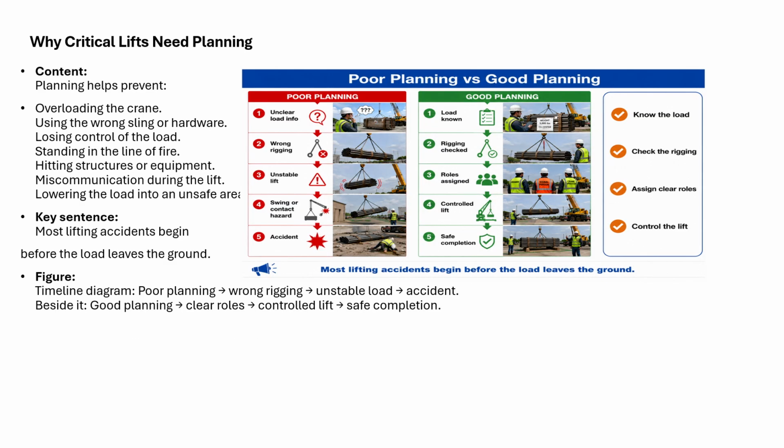Why does a critical lift need planning? Planning helps prevent overloading the crane, using the wrong sling or hardware, losing control of the load, standing in the line of fire, hitting structures or equipment, miscommunication during the lift, and lowering the load into an unsafe area. Key sentence: most lifting accidents begin before the load leaves the ground.